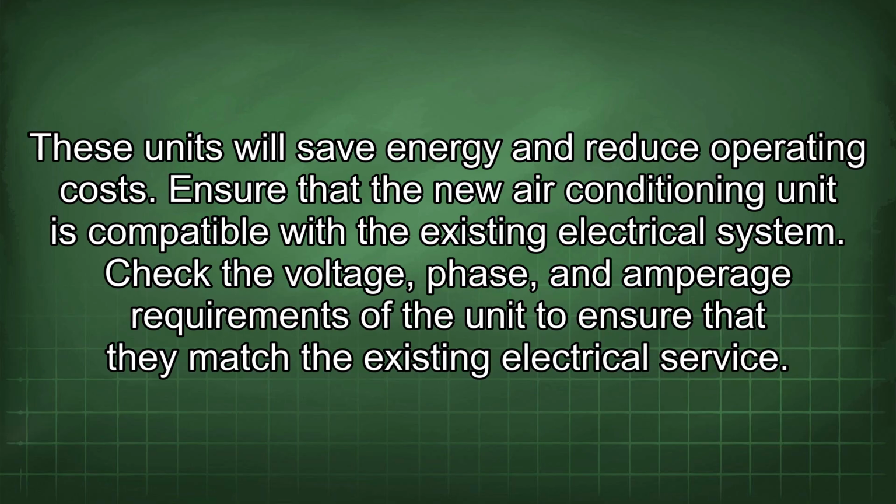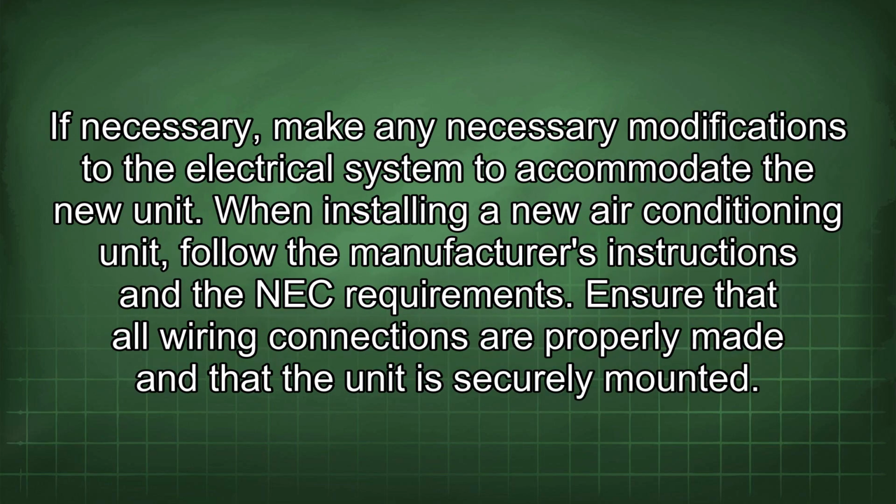Ensure that the new air conditioning unit is compatible with the existing electrical system. Check the voltage, phase, and amperage requirements of the unit to ensure that they match the existing electrical service. If necessary, make any necessary modifications to the electrical system to accommodate the new unit.